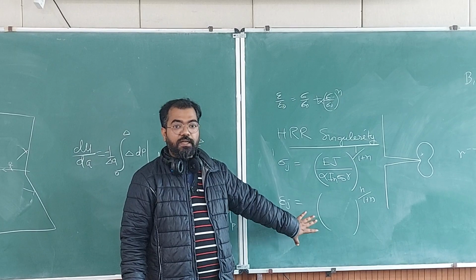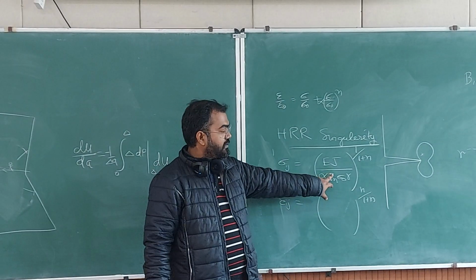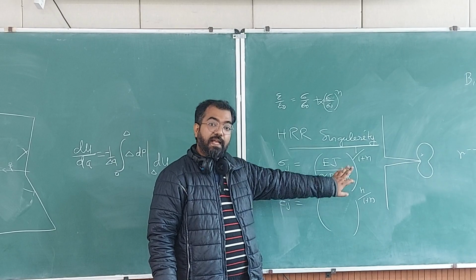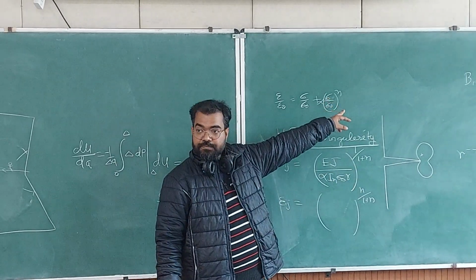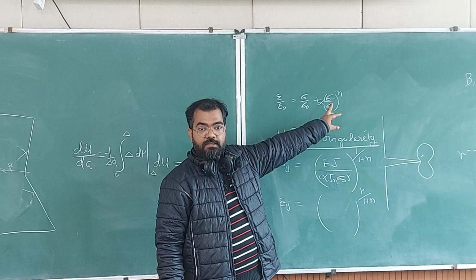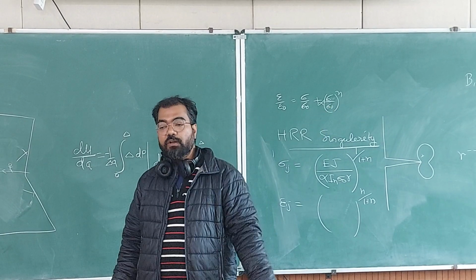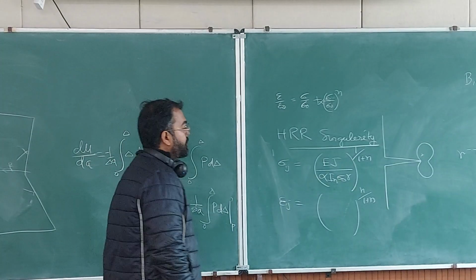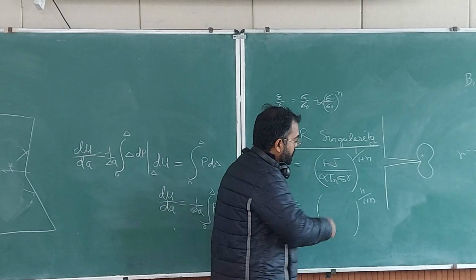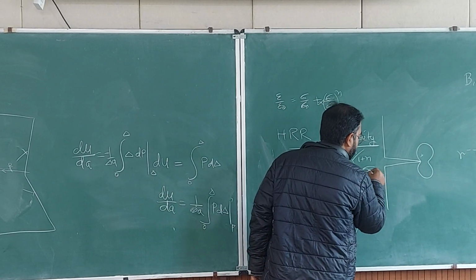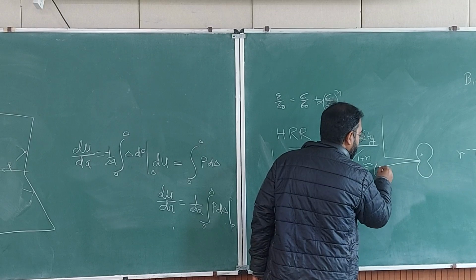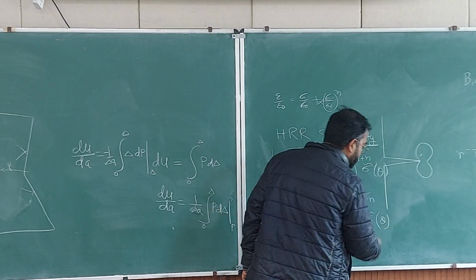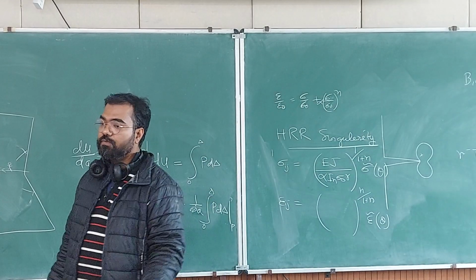And in order to calculate those things, you need the value of J, you need the value of I_n. I_n is an integration which is a function of n. What is n? n is that. Okay, n is the strain hardening exponent for the Ramberg-Osgood equation. Okay, so the values of sigma-tilde, you also have as functions of theta here. Okay, because it will also be a function of theta.